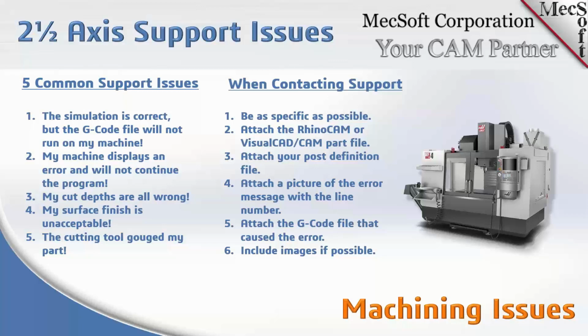If you're starting and stopping at the same point and you're cutting a soft material, depending on the perimeter curve, if it's a 3-dimensional curve, some tolerances can come into play so that you start and then stop at not the exact same point that you started. So tolerances can build up. Again, that has to do with accuracy issues. So you may see a little dimple on your cut start point. So those are some things.